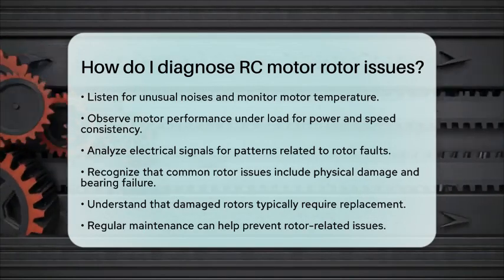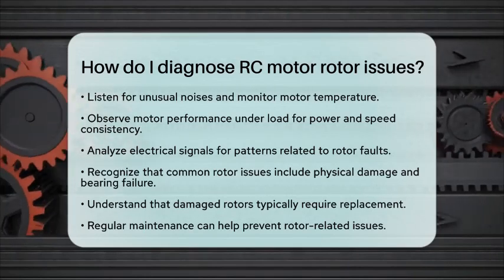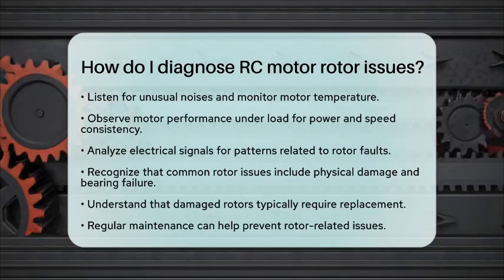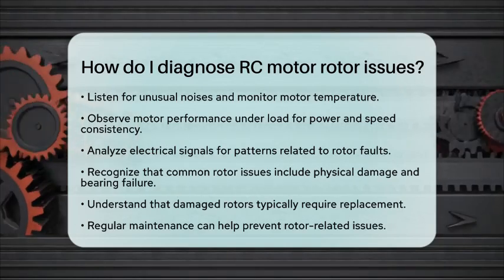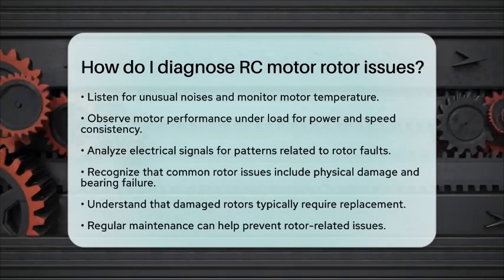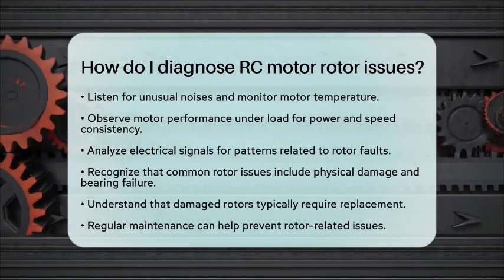Regular maintenance, including cleaning and bearing lubrication, can help prevent rotor issues. By combining visual checks, mechanical feel, electrical measurements, and operational testing, you can accurately diagnose rotor problems and decide whether repair or replacement is needed for your remote control motor.